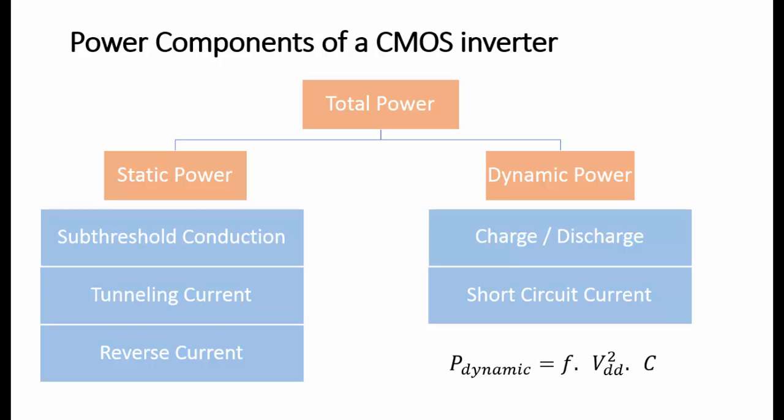For fast input transition rates, the dynamic current is governed by the internal capacitance and the charge and discharge current of the load capacitance. Dynamic current is dominant in CMOS circuits because most of the power is consumed in moving charges in the parasitic capacitance in the CMOS gates.